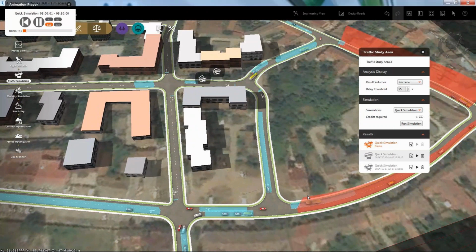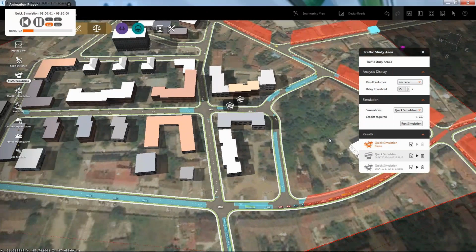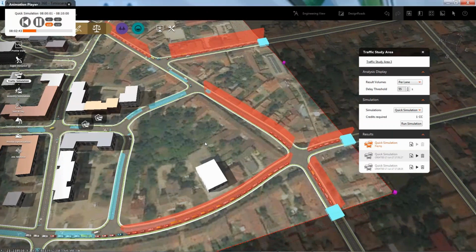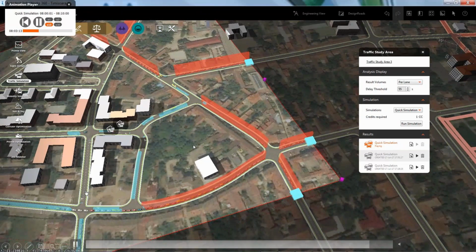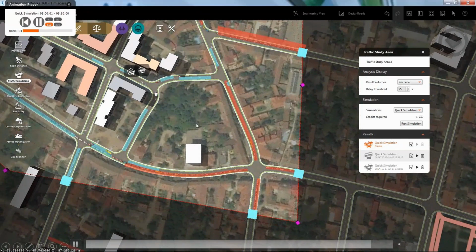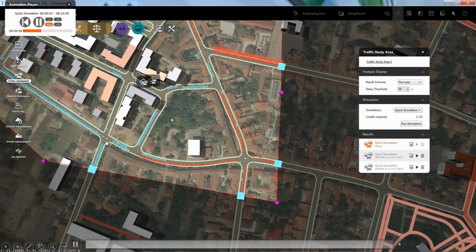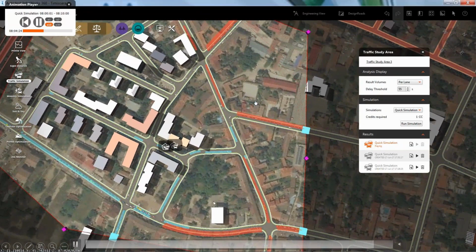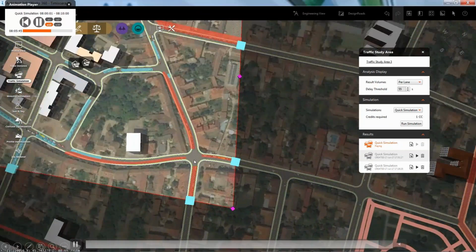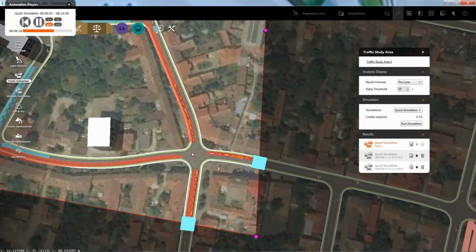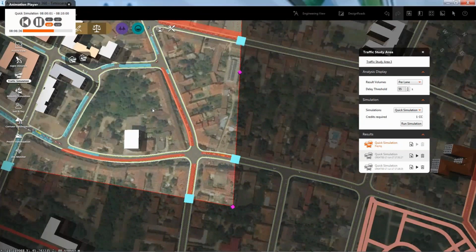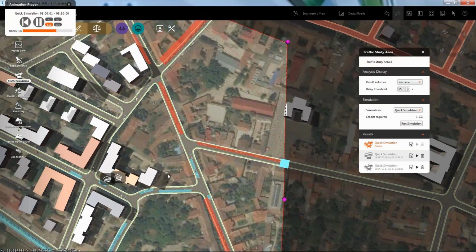So basically I shown the results, and in red areas there will be really trouble because people will be packing, and you can see that now this road here is closed, no traffic is going through, so people are passing only here, but it generates much more traffic going around. And here this road, obviously people want to go left, but they have to wait to the other people, etc., etc. So maybe the next step should be in this junction to make traffic lights, because so far there is no traffic lights, so that maybe I should put there temporary traffic lights and analyze it again.